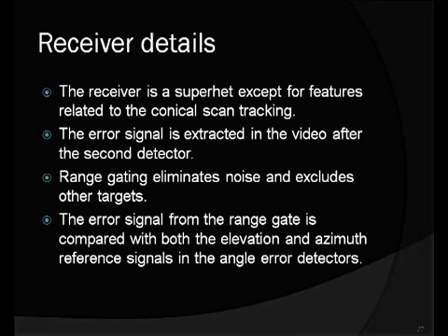Similarly here, the echo signals coming from different ranges are processed in different receivers. For this, we will have separate time domain filters which will be receiving the signals from different ranges. By this, we will be able to eliminate lot of unwanted signal from the stationary targets at different ranges.